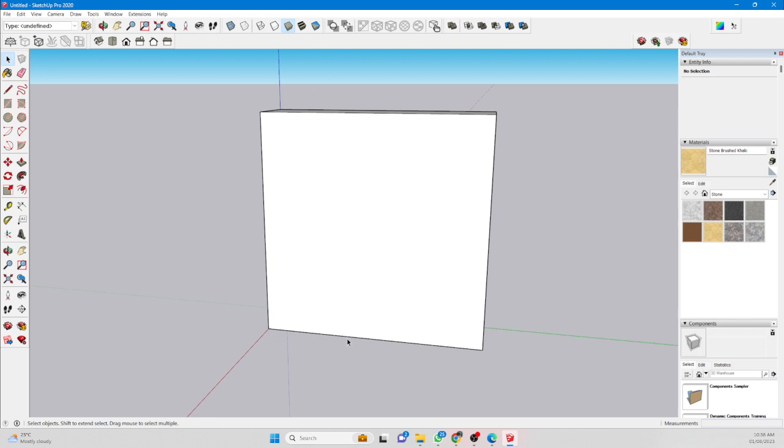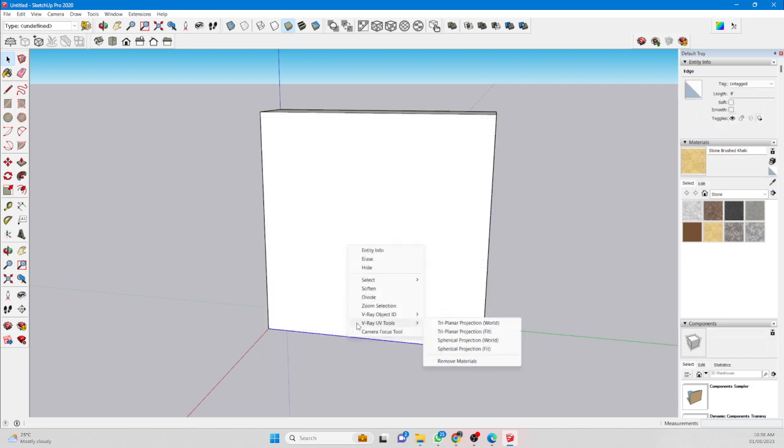Click on the line, right click and choose the divide option. See, if we move the cursor, the points increase or decrease. Do we want 5 doors or 4 doors? We'll give 4 doors.